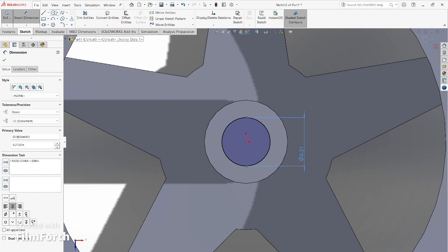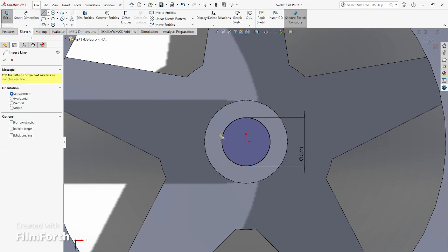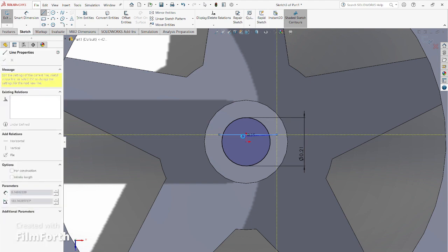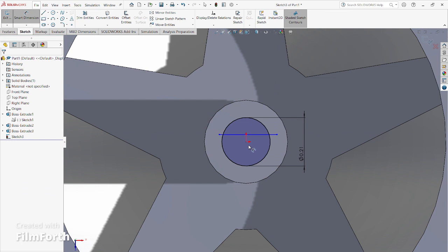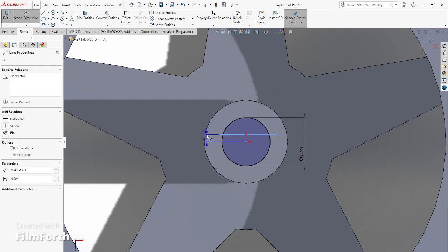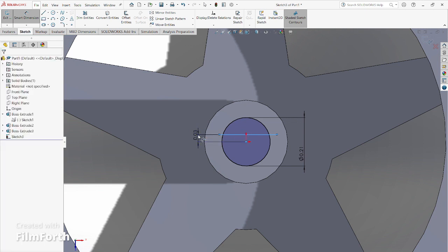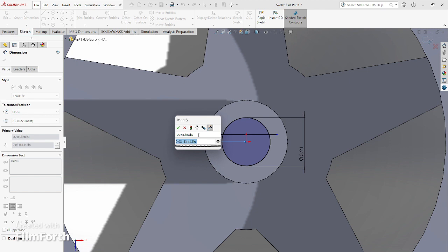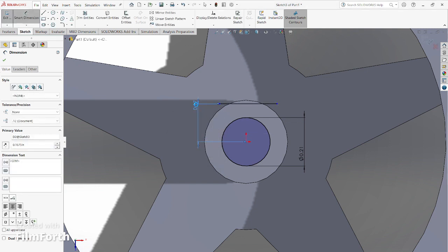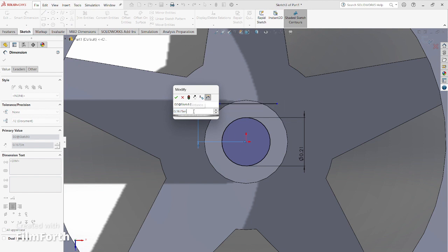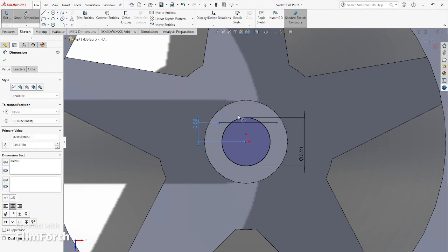Okay. The next one is our line. I'm going to make our line, bring it from here straight across onto the circle. I'm not worried about doing the other side. I'm just going to focus on one side. That's it. So use the dimension, go from the orbit to the line, and from there it's going to be about 0.1635. Same thing again, plus 0.004. So that should give us a... wait, and divide by 2, because again we're doing half the section.